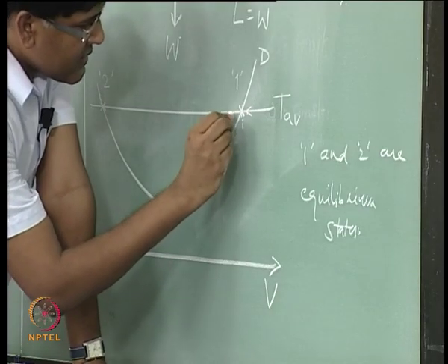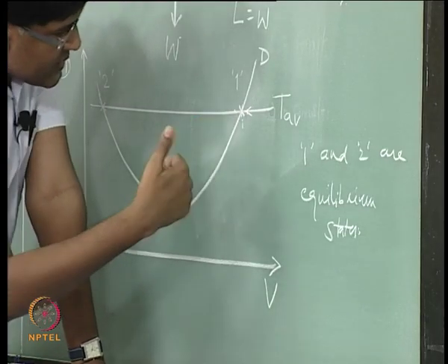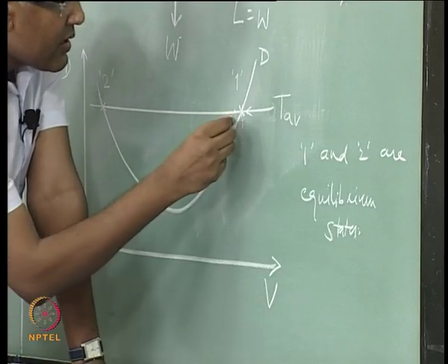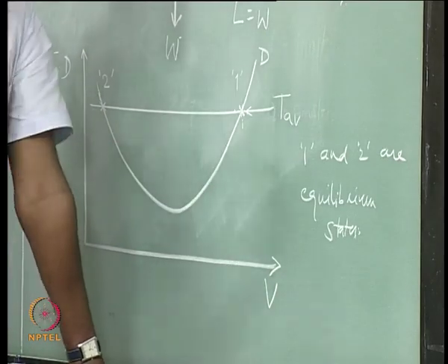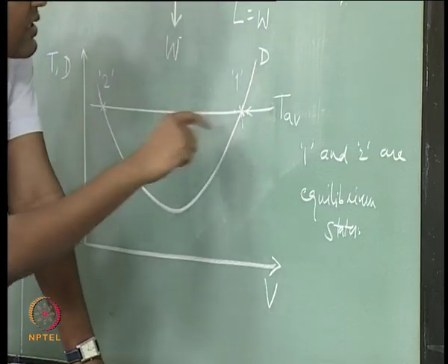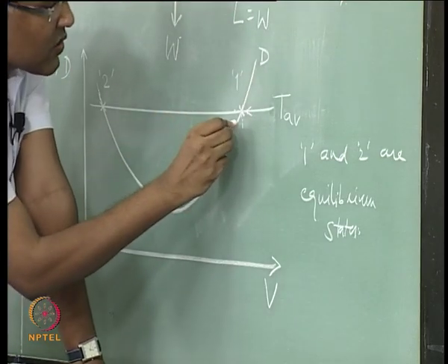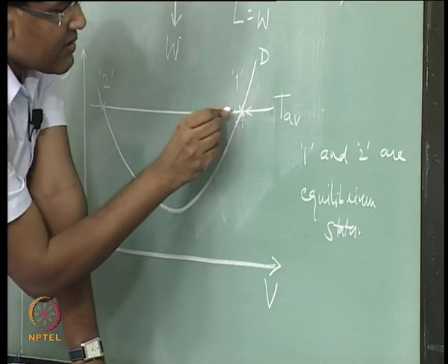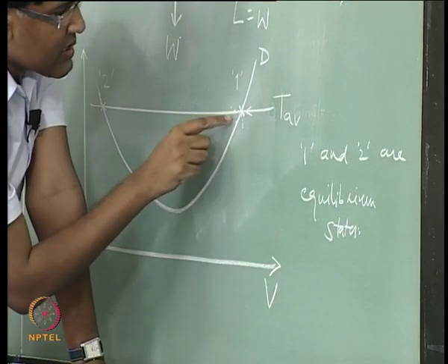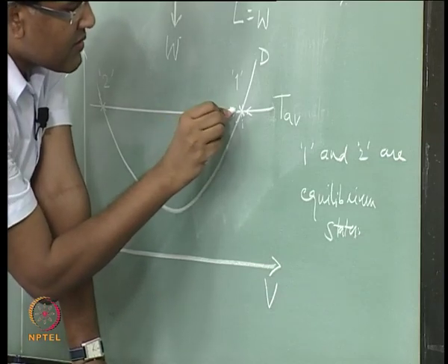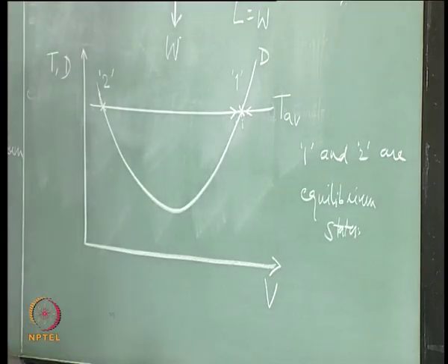On the similar lines, when the perturbation results in change in velocity in the negative direction, so the speed of aircraft in the forward direction is reducing, then the drag goes down and the aircraft will accelerate because thrust available is more than the drag now. So, let us put an arrow like this.